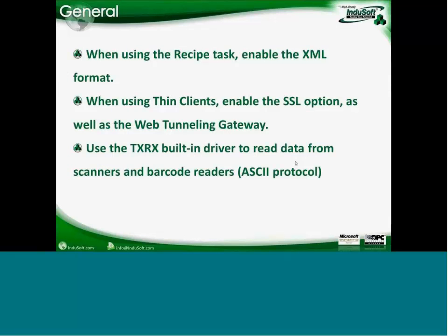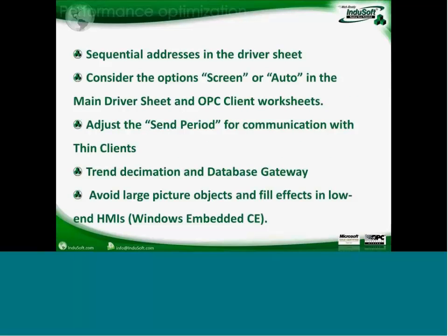Another tip, we have a built-in driver called TXRX, which implements ASCII protocol, so it's very common to use this driver to read data from barcode readers, RFID readers, that just stream the information through an ASCII protocol. And with the TXRX driver, you can very easily get the information from a barcode reader, RFID reader, or scales and get this information into a string tag.